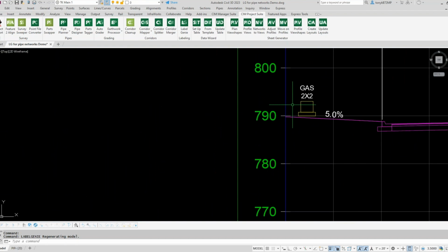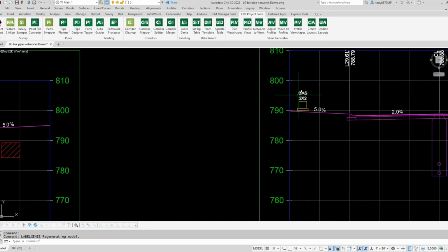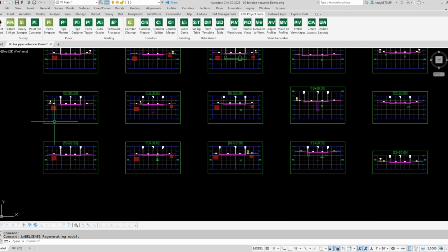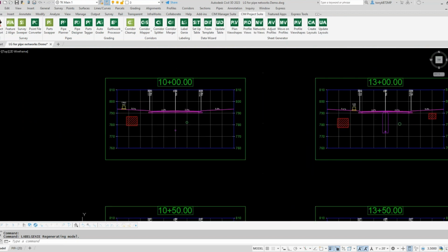So obviously I played with the landing point before of where they went. So let's do these electric vaults here real quick. And these were brought in just manually into these sections as blocks. I should mention that. If they're part of your pipe network, you can label them using that too.